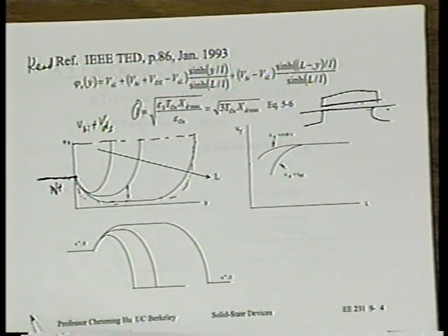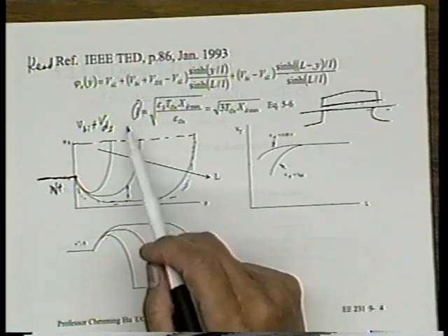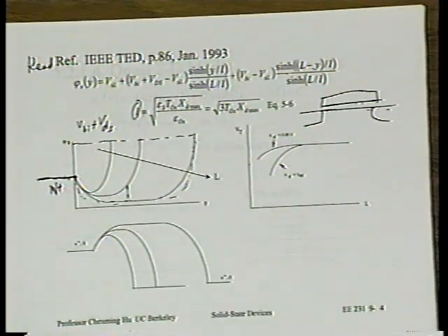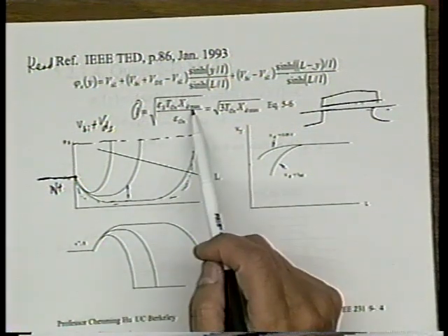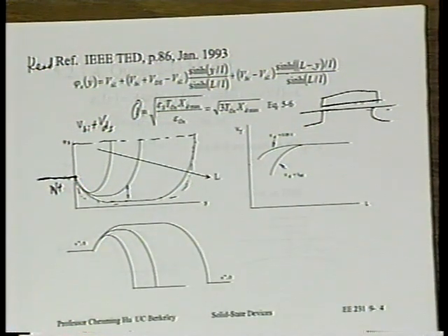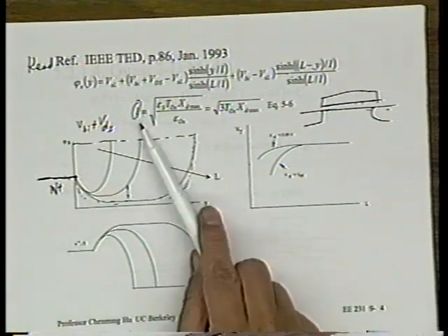Do you see what I'm saying? If I can make the oxide very thin, the surface potential will be very well controlled by the gate voltage at every y. In fact, if the gate oxide is 0, the surface potential will be equal to the gate voltage. Since the gate voltage is not a function of y, there will be no drain barrier lowering effect. See what I'm saying? Okay. That's why when Tox is small, we have a very short decay length, which is what we want. If the depletion layer is thin, we also have a very small decay length.